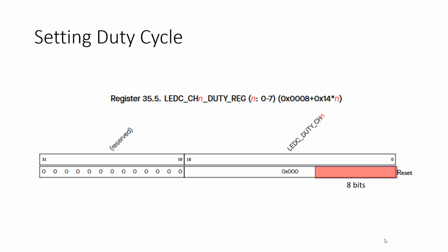Why do we have 19 bits? Might the S3 go higher than 12? I don't know. The regular ESP goes to 12. Maybe the S3 goes higher. Yeah, because Alex just got done explaining that there's no way that you can have more than 12 bits. Regardless, but still at our clock frequencies, you still can't use all of them because the counter would keep overflowing. Yeah. But maybe it does go higher, I'll have to look that up.